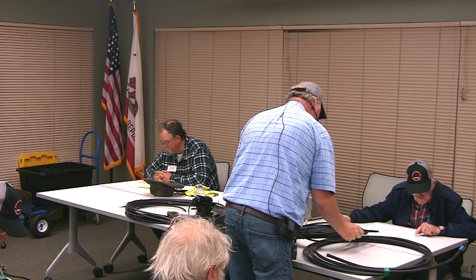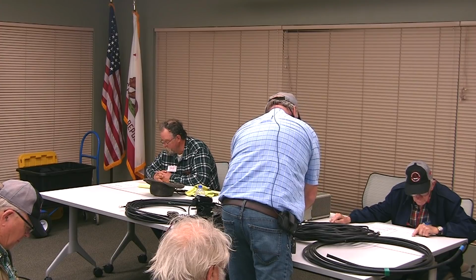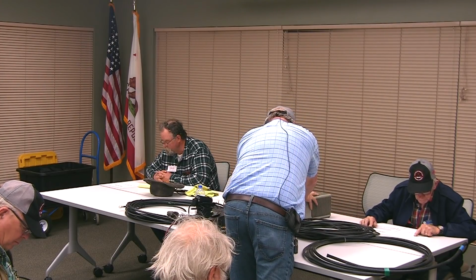So we're going to check it on 2 meters first. I want you guys to give an estimate of what you think it's going to be. We're going to do 80 feet at our 147 megacycles, and we know what our reference is, 42, and now there we got about 23. So you guys tell me what you think the loss should be. 1.6? Yeah, that's right. That's really close.